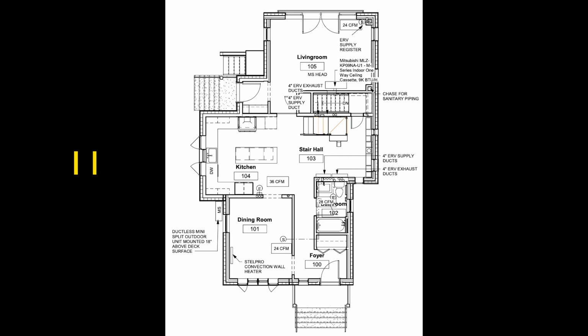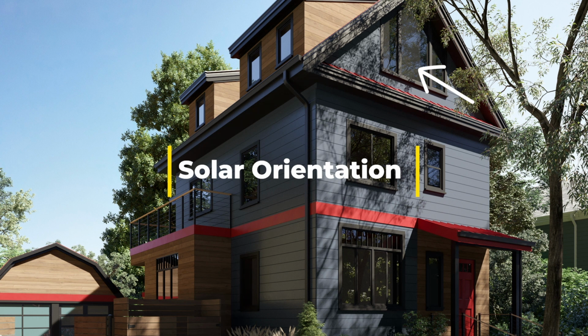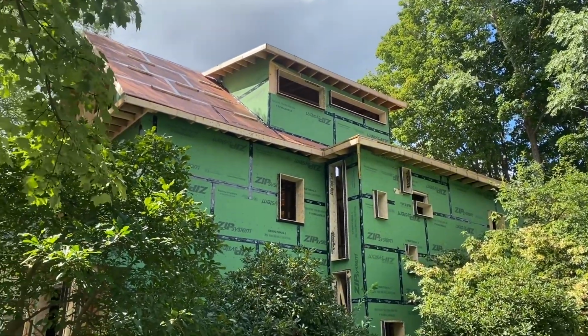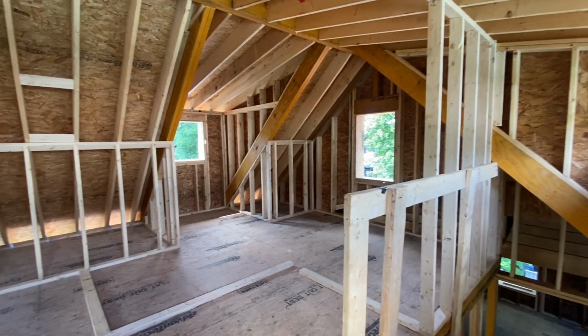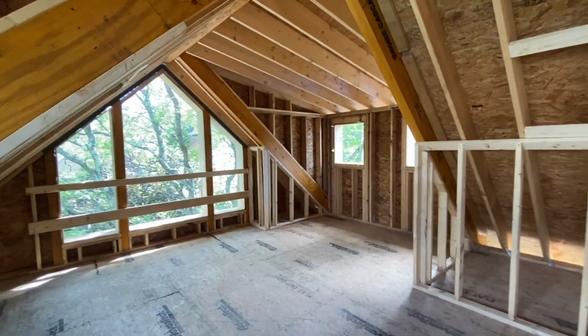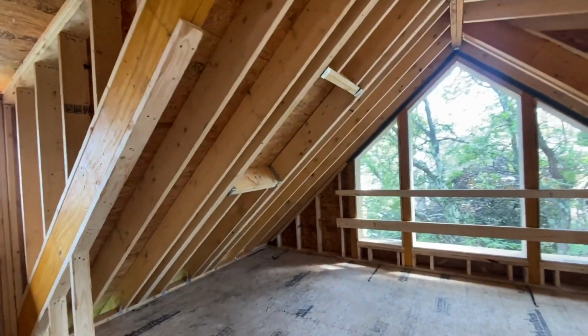And so the last factor for a passive home is solar orientation. This is a remodel. So the home, we couldn't particularly change the orientation, but what we could do is decide where windows are going and be very exact on that. So that was the north side. You saw smaller windows there as a result. Whereas on the more southern facing side, where we have the opportunity to bring in a lot more sunlight, we did so. And you can see that here. We're extremely excited about this home.